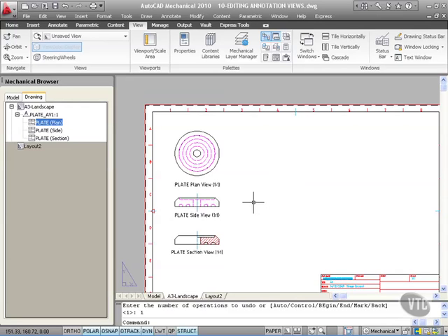You might click undo a few times and think, oh, it hasn't changed. I'll leave it, delete it, go back to it. Don't do that. Undo as far as you can to make sure that you can see what's going on. Undo is a very useful command, but it can be used erroneously, like I've just proved. Make sure you undo all the way back, because there's 4 or 5 steps there when you actually change your label, when you edit your label in your annotation view. So as you can see there, annotation views, easy to edit as long as you're careful.